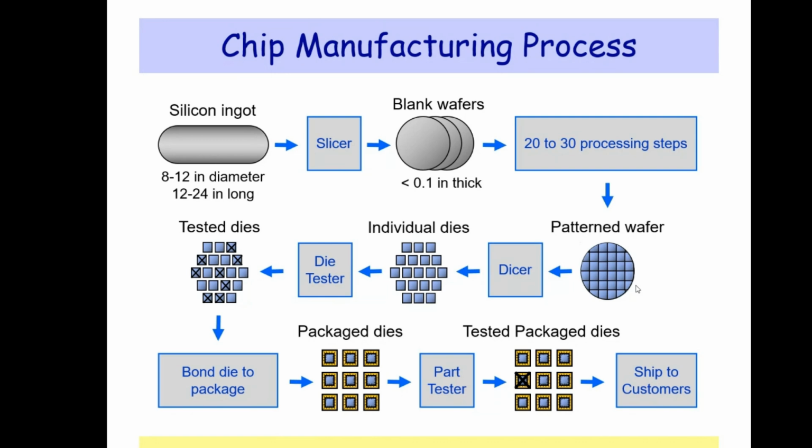most of the dies will be in a bad shape, so that you cannot bring up your IC there, because in that particular die the silicon is not proper and the connectivity is not there properly. So there could be many process variants and temperature metrics it is not meeting. So you will discard these bad dies, and only the good dies will be moved on to die packaging.